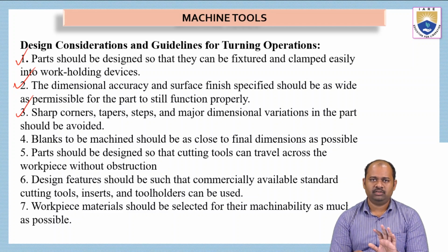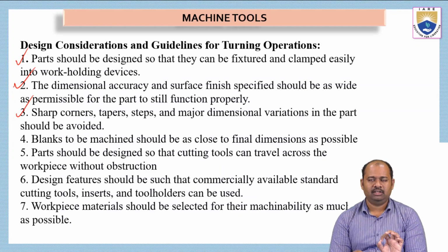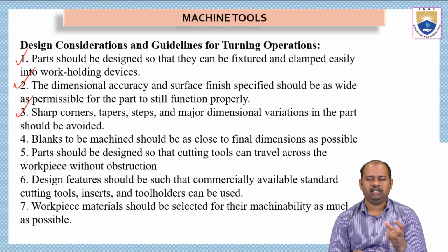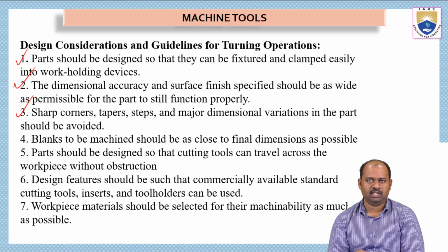So sharp corners should not be there. Taper turnings should not be there. It should be done by a skilled person. Step turning should not be there. This will increase the stress concentration in the body. So taper is good. Step turning is not good because it will increase the stress concentration at particular areas.